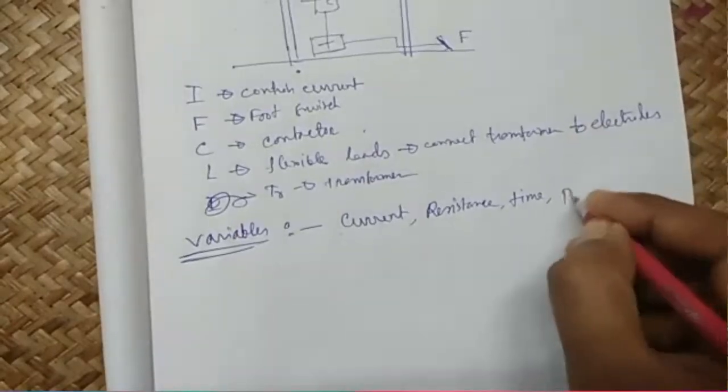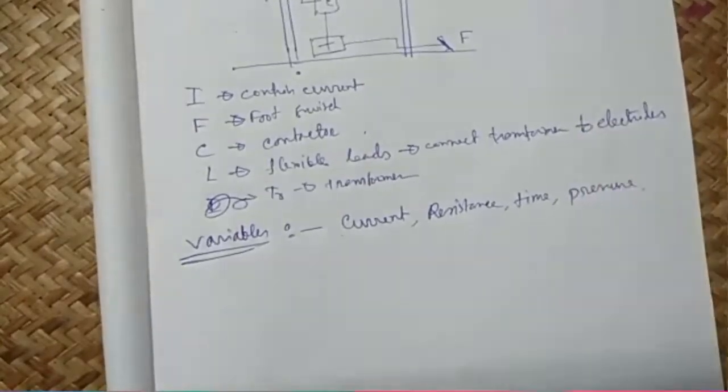and the pressure also. You have to apply enough pressure that the joint should not move, and the resistance becomes lower. Correct contact is to be made. Otherwise, it will become very difficult. And if we apply more pressure, then the surface will be ruptured. The job material will take the shape of the tip of the electrode under high pressure. Pressure has to be controlled also.